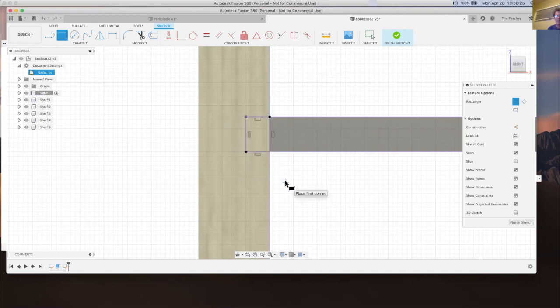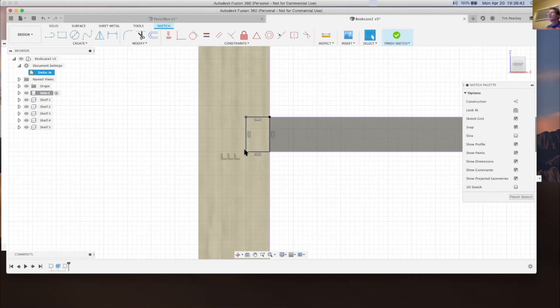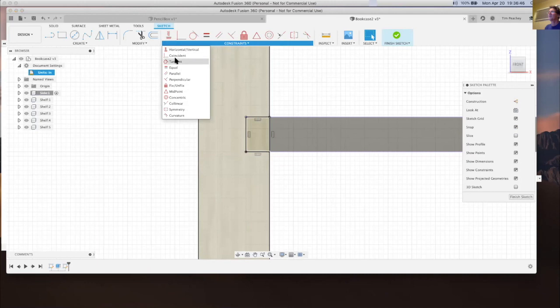What you see on my sketch is these lines have snapped to be horizontal, vertical, horizontal, vertical. And these constraints here tell me that, I see that shape. What's that constraint? That constraint is coincident. So the corners are coincident here, corners are coincident here, and that fully constrains my rectangle.